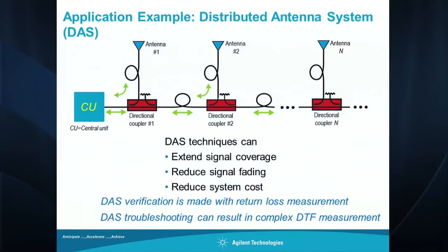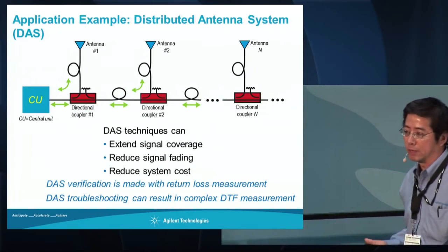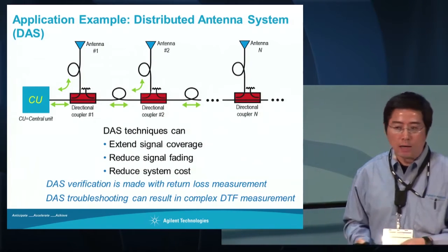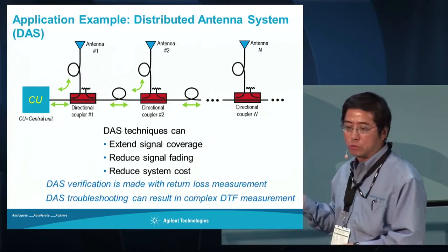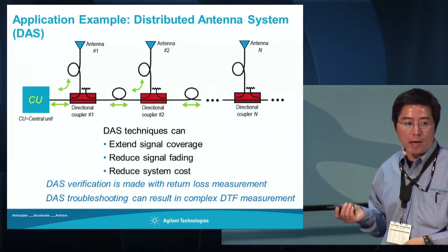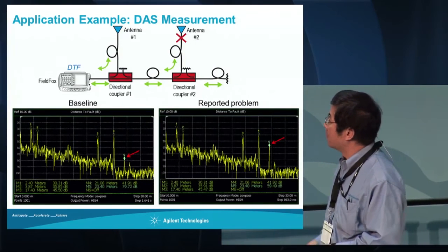You don't want to use one antenna just blasting everywhere, where you get all the reflection. You're not going to get a good service. And so people start to use very low power transmitters inside the building. And of course, you need cables, adapters, and splitters to distribute the signal. Distance to fault measurement and return loss are critical here. Distance to fault is a very neat tool to help you identify the problem in that system. So this is a demonstration.